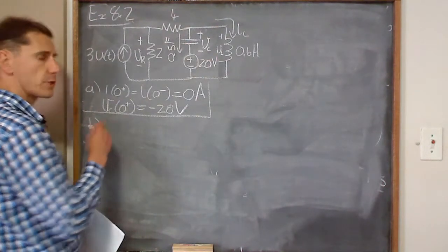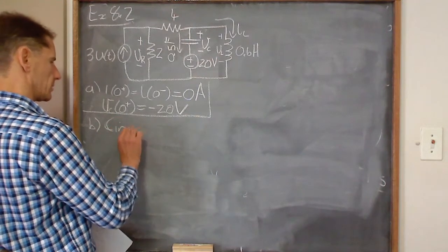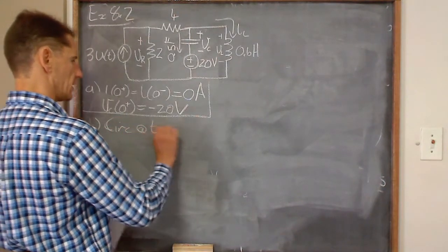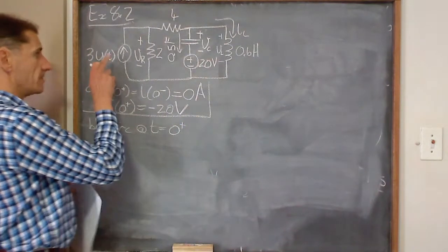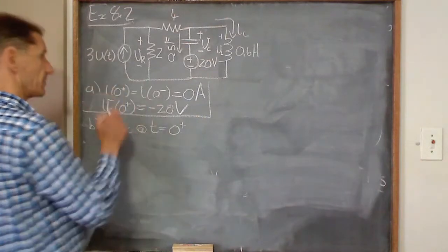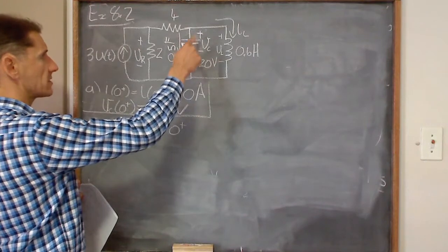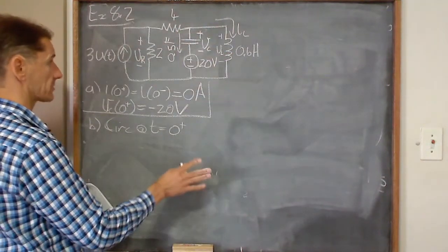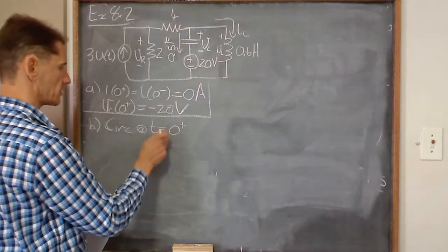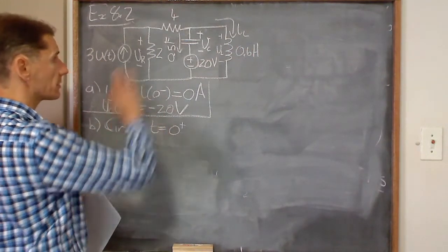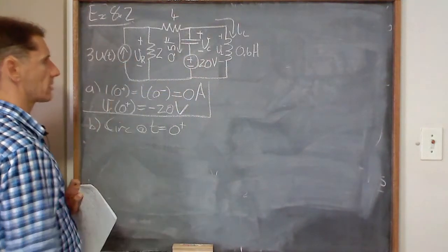So we know for the DIDTs already we're going to need the circuit at t equals 0 plus. So what happens then? At time 0 plus, that source kicks in. That one is still there. Capacitors there, inductors, everything is there at time 0 plus. So we just need this circuit diagram to solve for time 0 plus. So we don't need to redraw anything. We're just going to use this circuit diagram with that current source now in.